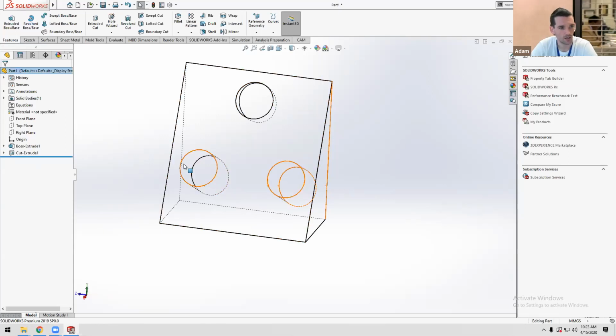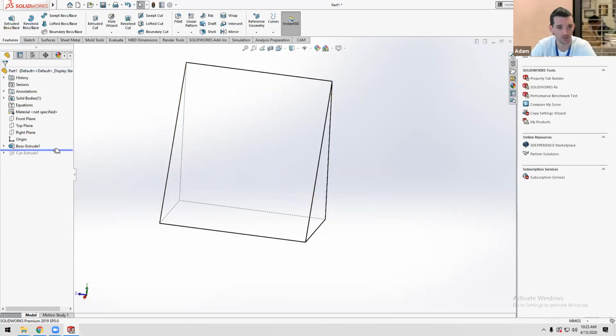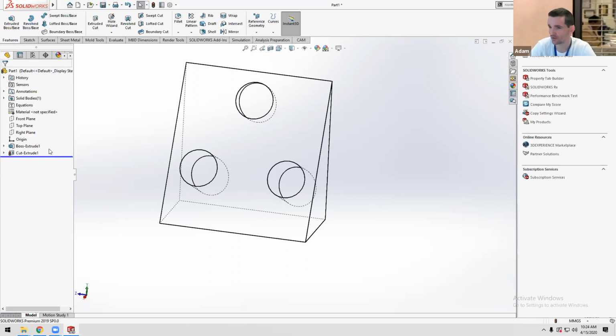Okay. A powerful thing to make design changes or edits is to use the rollback feature, which means I can drag this line backward through my feature tree or order of operations, and I can start doing some other functions here, and this will just get pushed to the end. That also helps you if you downloaded a model from GrabCAD and you want to see how it's built in that order of operations. You can use that dragging to go step by step and watch how they did it.